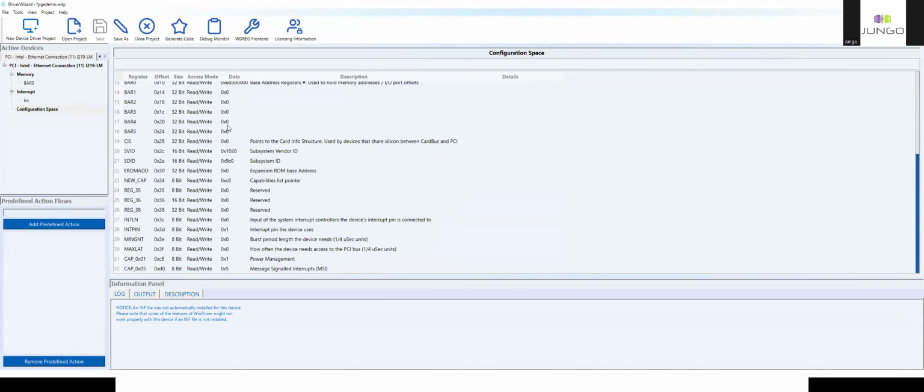Once my device is identified as PCIe, I was able to open it, and I can see the configuration space data. I can see the memory BAR, which I have only one of here. I can add access registers, read or write to the memory, listen to interrupts, and add transfer commands that will be initiated after the interrupt is raised. I won't get into other features right now.